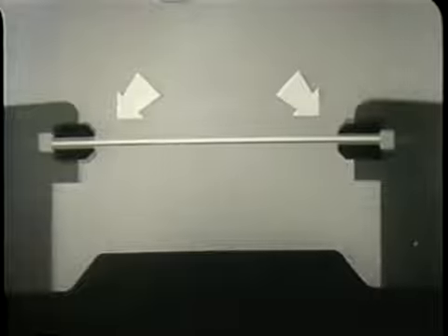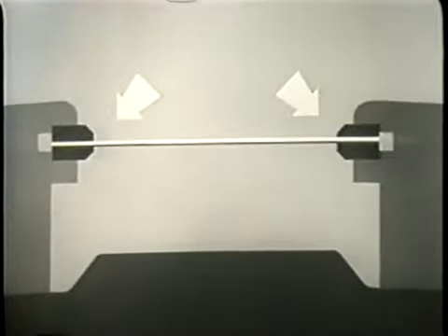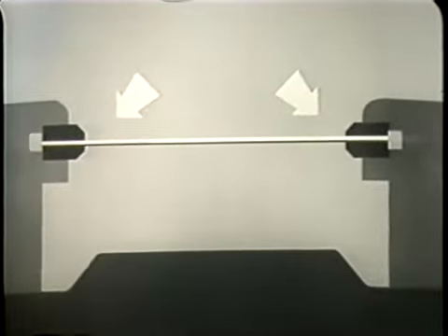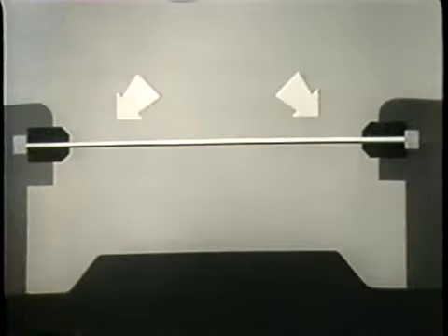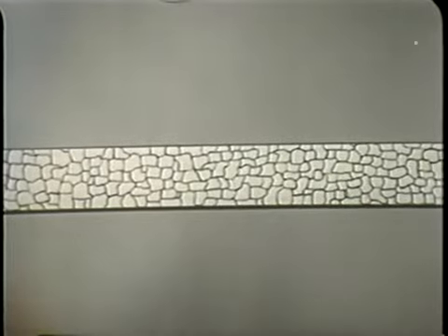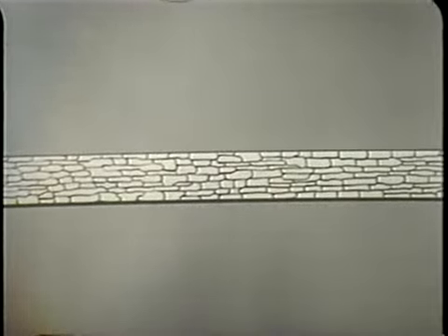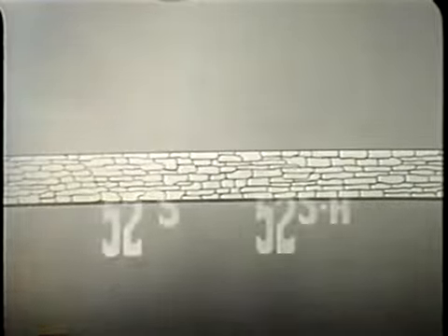The stretching process is based on the action of vise-like grips, in which the edges of the aluminum alloy section are inserted. As the tensile load is applied through the grips, the metal is stretched, the equiaxed grains becoming elongated and oriented in the direction of the applied load. These grain changes increase the strength and hardness of the metal.